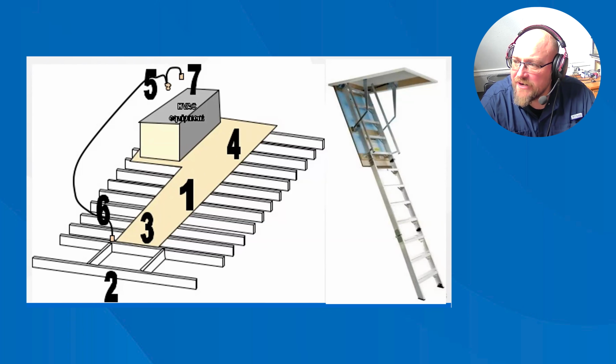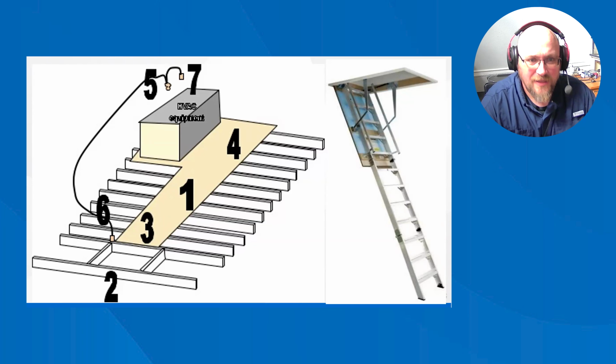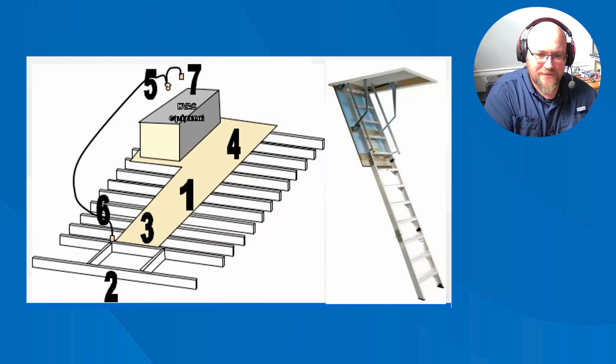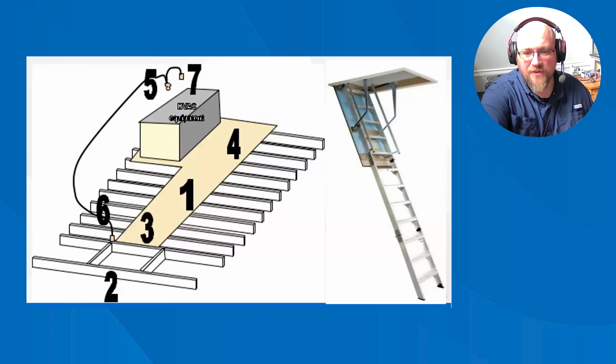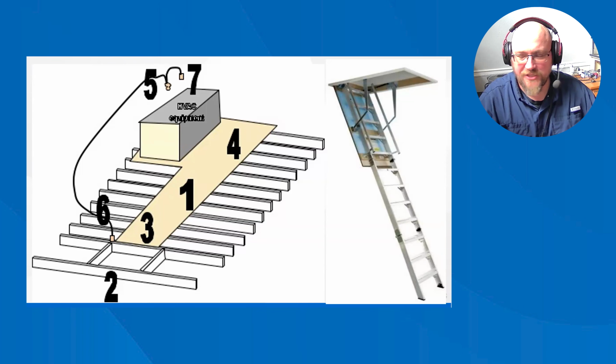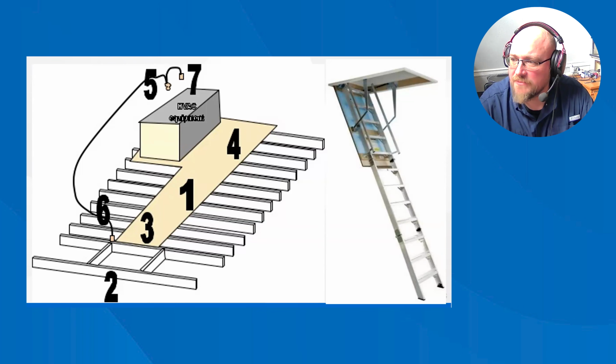A service area is required in front of the mechanical equipment. Again, that is often missed where they might put a walkway, but then they set the HVAC system off of the walkway and they don't complete that landing that goes from the walkway to the unit itself. That's a very common observation. The dimensions should be at least 30 inches by 30 inches in front of the unit.